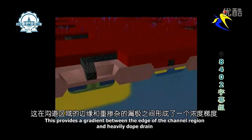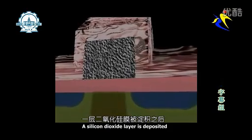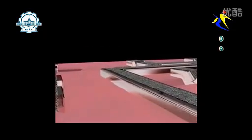This provides a gradient between the edge of the channel region and the heavily doped drain. A silicon dioxide layer is deposited and then etched vertically. This creates oxide spacers along the gate sidewalls.